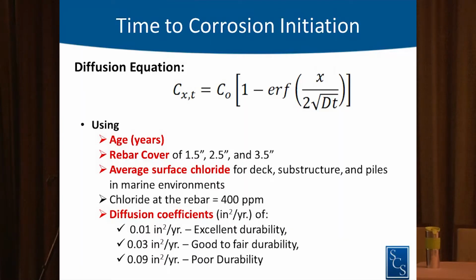Concrete is like a hard sponge. You look at it as a hard sponge with holes in it. Some of it, we actually design holes in and distribute the holes so that you have freeze thaw resistance, right? But generally, even if you don't design, concrete has holes in it, and the water goes through it, salt goes through it. And so the question is, how do we figure out how fast it goes, right? It's the property of the concrete. And that's what we want to measure with the diffusion coefficient. We are measuring the property of the concrete.